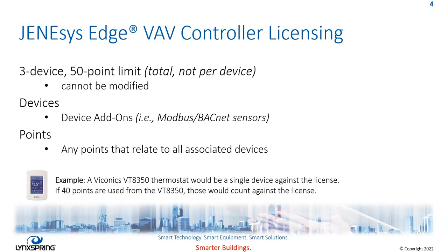Now, because this is a fixed license, it has a lifetime SMA, which means that you can upgrade this to whatever version of Niagara 4 that we offer with those Edge files for the lifetime of the controller. The SMA does not expire. Also, because it's a 50-point limit, it's under even the 100 points that would be required for an Edge Lite controller. So this actually will be an Edge Lite device, which means that you can have 10 of these per Niagara network connection.